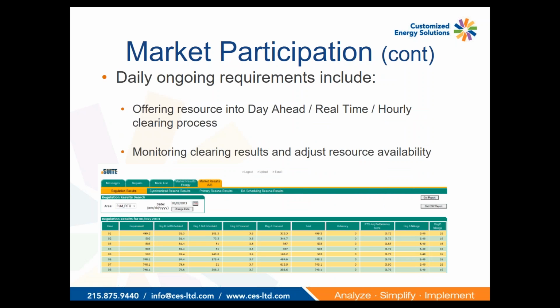Then once you're participating in the market, just to give an idea of what's required day in and day out, most of the ISOs have either a day ahead or real time or some sort of hourly clearing process. So normally some steps have to be taken in the ISO scheduling systems to keep those resources in the markets. Some of them do have the capability of just setting one offer and letting it roll over and roll over. But then all of the markets, you'll need to be monitoring what the clearing results are and potentially adjusting the resource availability into the market.